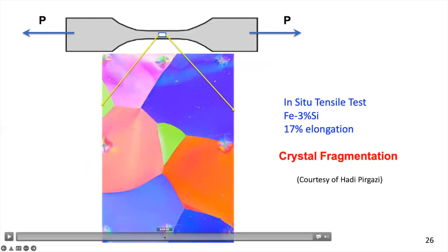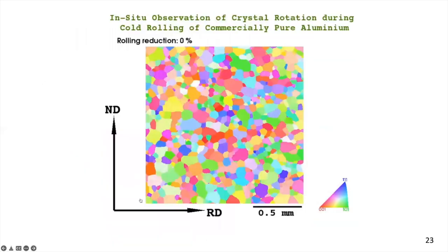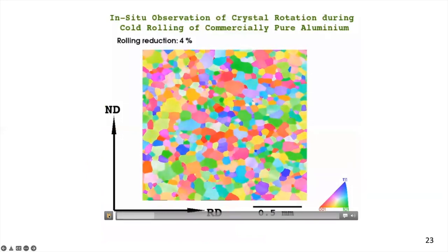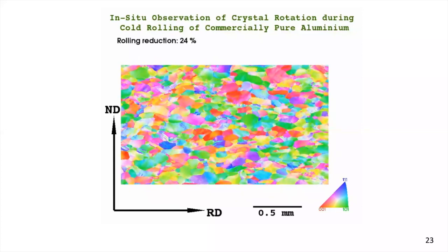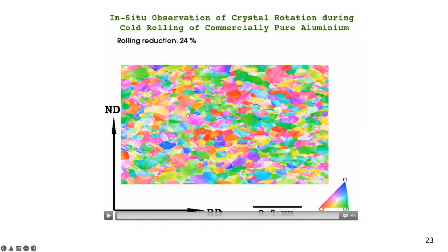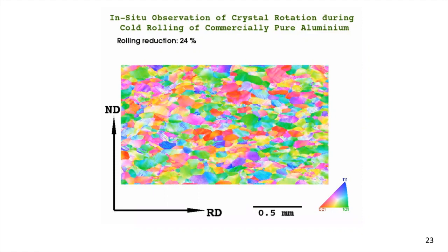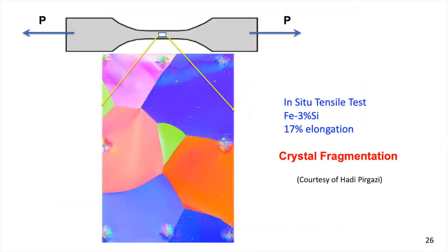And actually, if you look here at the image, you observe two important effects. Of course, the shape of the grain, the morphology, changes, but that's not what we are talking about here. We are talking about the color. You see that the color of the grains changes, but not only that, you see also that the colors inside the grains change. There is a gradient of crystal orientations, and that's shown even more explicitly here.